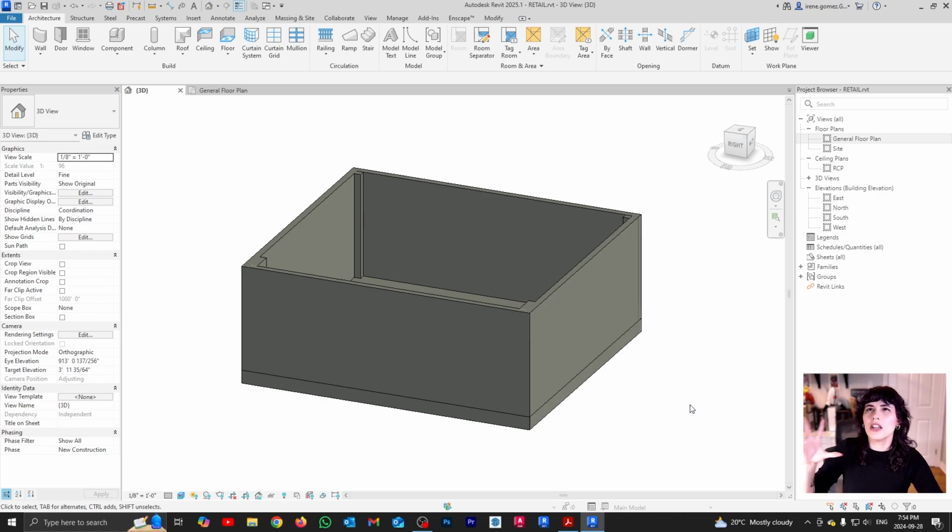This is super important. If you don't do that, if your floor only follows the walls and it ignores any protruding columns, your 3D model is going to look kind of weird. It's almost going to look like your columns are just hanging with their feet out in the air. So you want to make sure that your floor boundary covers everything on top of that floor.